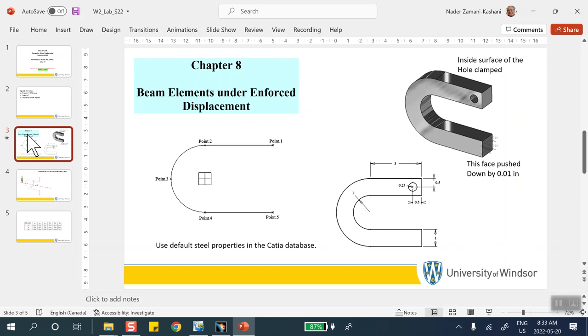Is it this location, top fiber, bottom fiber, neutral fiber? So to get a plot for you, it's kind of become meaningless perhaps. Some other software do it, but then they decide where they're plotting the stresses. Of course, even there you can set those things, but CATIA won't let you do that, bottom line.